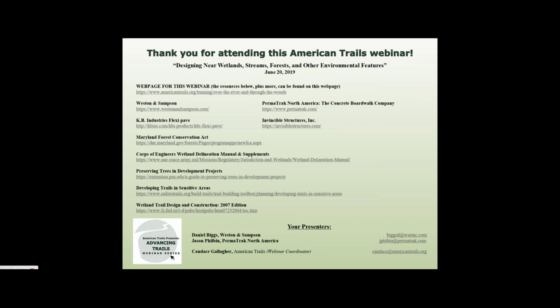Advantage of a wood is that it would have the aesthetic appeal that the wood has, and it would last longer than the timber. So those are a couple of items there. The downside on the timber is that, first of all, it can be very slippery. The composites can be very slippery. The wooden boardwalks generally, especially in the moist climates or the harsh climates, are going to curl and rot and twist and decay, and then the fasteners could unravel and pop, and that just requires maintenance. So generally with a timber boardwalk, you're going to see much higher maintenance costs.